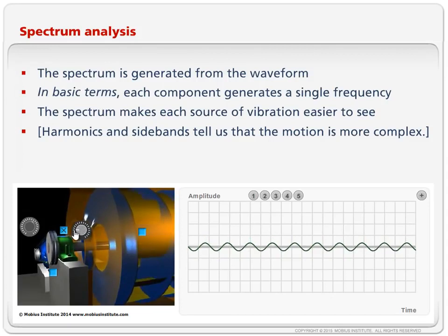Now, if the bearings were in tip-top condition, very good condition, I actually don't expect to see any green vibration. But as the problem develops, I get more and more green vibration related to the bearings. Let's turn that off for a second.